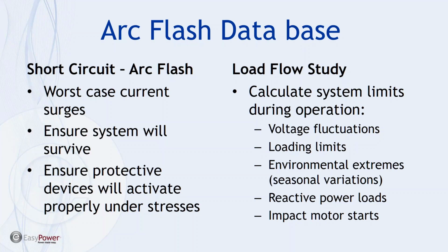Load flow might be something that we would want to incorporate in terms of our utility spin, whether or not we have power factor issues, whether or not we have motor start fluctuations that could be causing flicker or interference with other system operations that aren't necessarily obvious and could actually be obscured by some of the control systems we have in place.